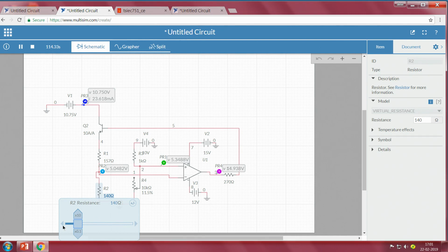As the resistance keeps dropping, your feedback circuit should work in such a way that it will inflow current, so that self heating happens through the resistor and it regains its normal temperature. That is, it should come back to resistance, so that the temperature is maintained at 157. Now assuming there is a lot of airflow and your resistance is dropping, keep a 130 ohm load.